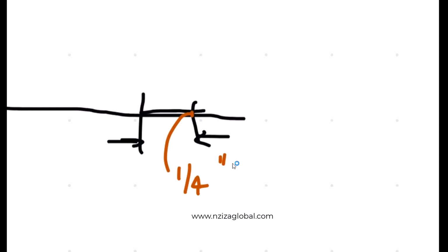All right. Going back to Revit now. Now what we need to do is we need to start, that was the floor above. We need to start drawing the pipes for the water closet. Okay. One mistake that you see that the architect did over here was the placement. They don't have it on the vertical wall. They have it on the floor. All right. So this is very common. This keeps on happening. Coordinations keep on happening. If you come across this kind of issue, please bring it up to your architect so that he or she can have it properly given.